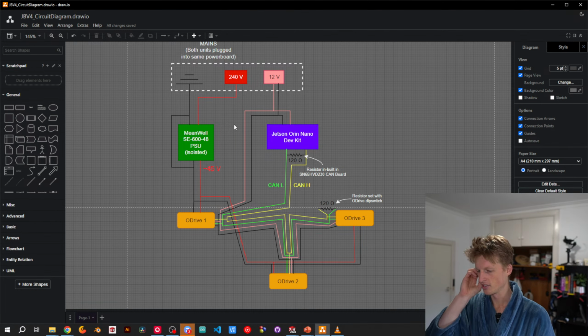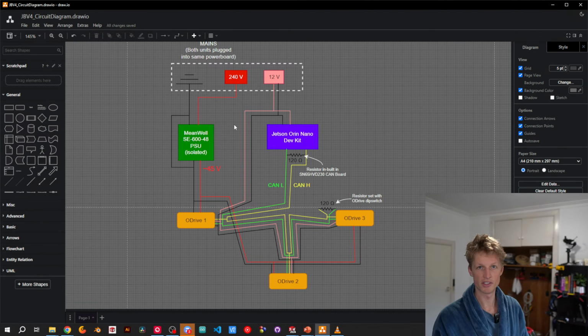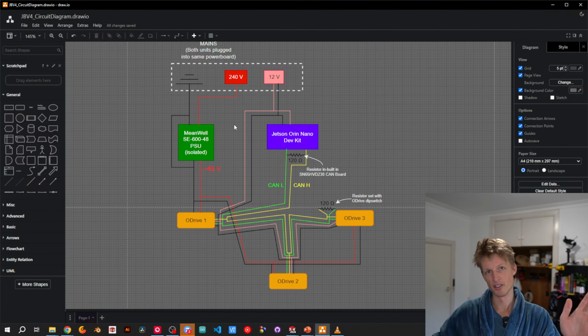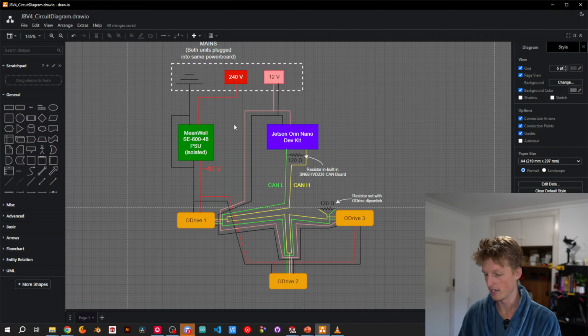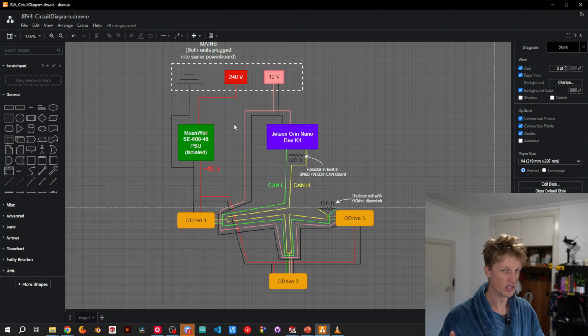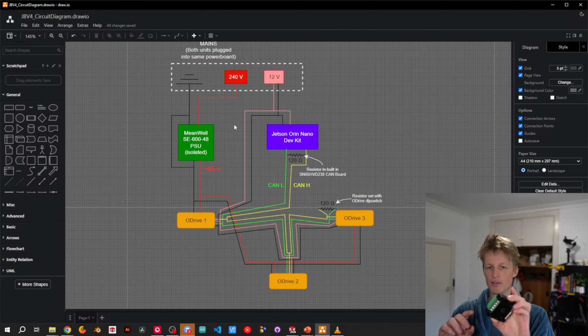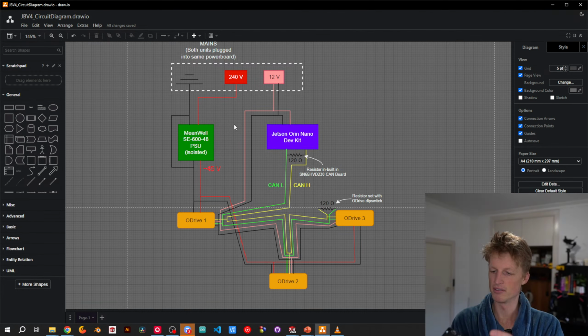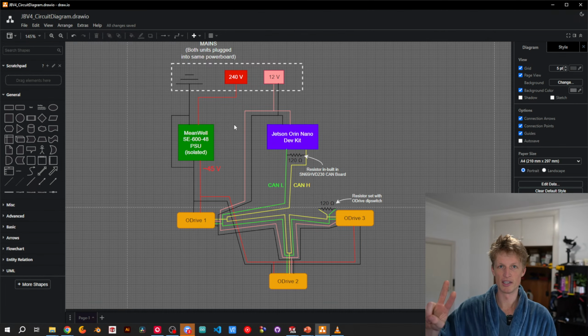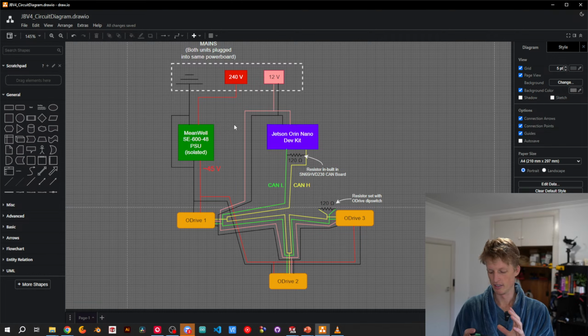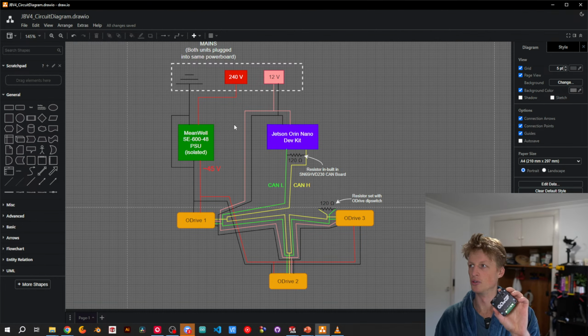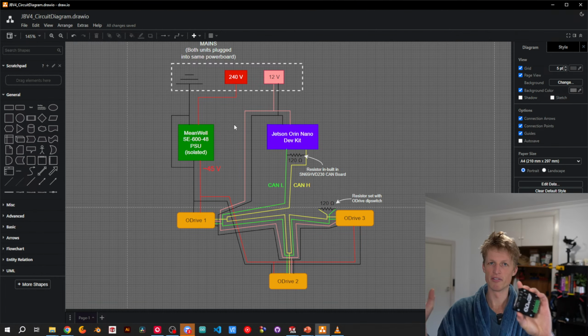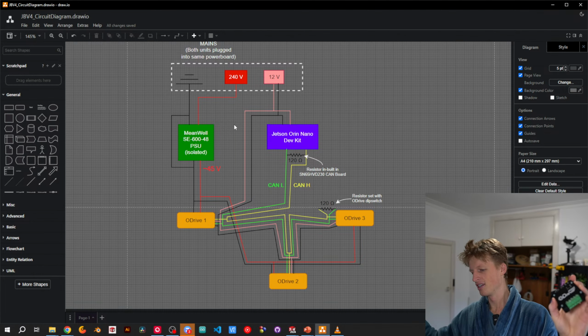And yes, something that I have discovered recently is that the Jetson can run on 12 volts, which is exciting. It can run between 9 and 20 for anyone curious, which is exciting because the ODrive Pros have 4 spots in their CAN connection. 2 are CAN high, CAN low. Third one is ground, and the fourth one is 12 volts. And that 12 volts is used in the ODrive to let you communicate with the ODrive when it's not even on, which is so good.